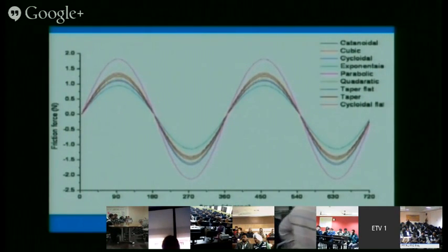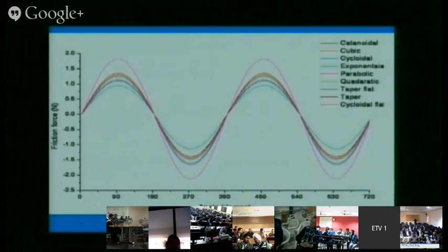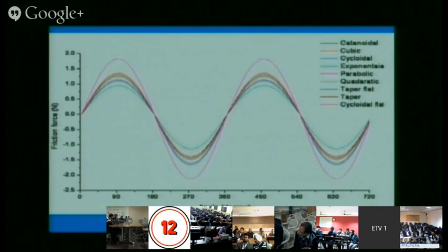Now what happens in the market: if you see piston ring profiles, these profiles are normally flat, hardly any shape is given. So the point I want to make is that if proper profiling is done, then huge savings can be made, and a huge reduction in friction can happen. It's fine. So here we are looking, particularly in this context, that the exponential profile is much better than the other profiles under investigation, and these are single continuous profiles.